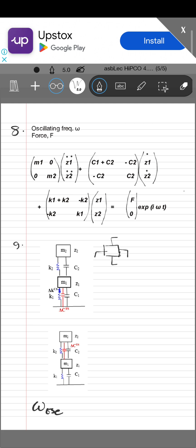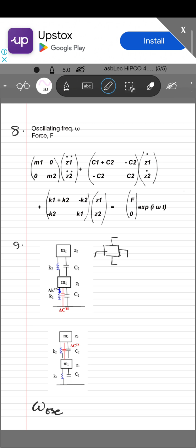a frequency is attached. Now, let's say you have a pedestal cantilever like this. Now, to this pedestal cantilever, next, if we assign a film, the antibody film to capture the PSA, deposition of the film is equivalent to having an extra capacitance in parallel with the capacitance C1. So this is basically the cantilever part. So to this an extra film has been associated.